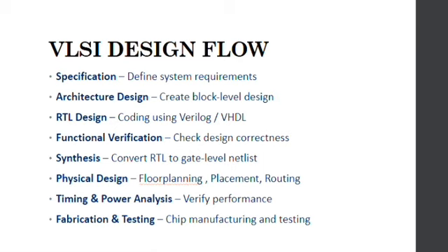Next stage is synthesis. Synthesis is the stage where RTL code is converted into a gate level netlist using logic gates based on timing, power, and area requirements. Next, we have the physical design stage, where the synthesized gate level design is turned into a real chip layout by placing and routing all the cells while meeting timing, power, and area.